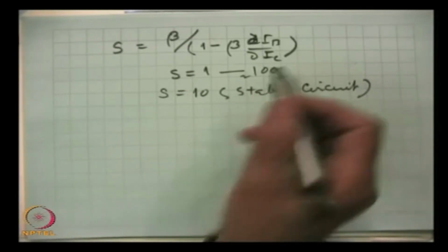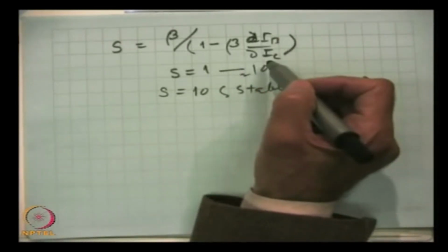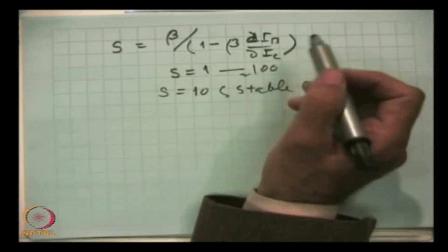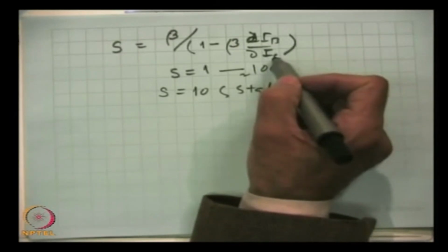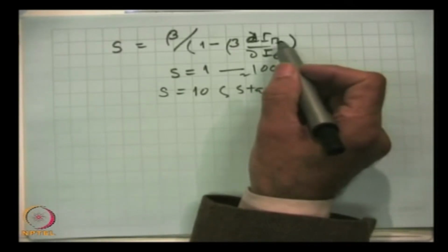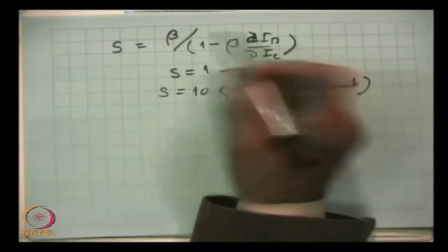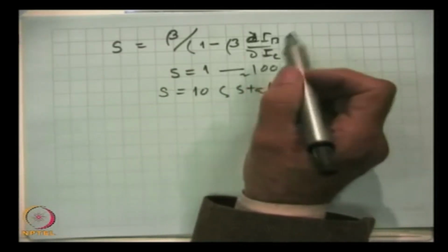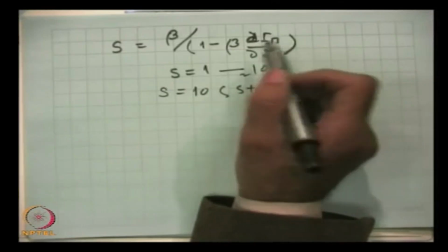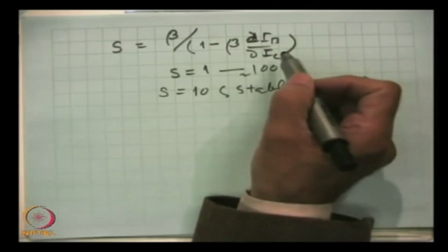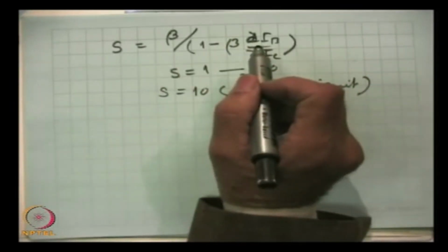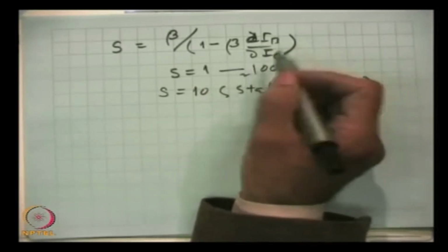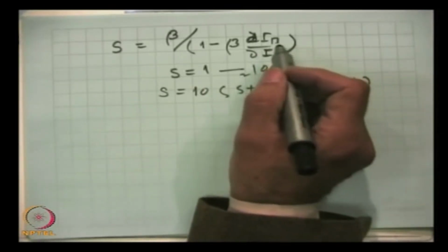So, what does it basically say? That in all circuits, when the collector junction is reverse biased and the emitter junction is forward biased, the output current will be a function of the input current. But here this says differently, that the input current should be made a function of the output current. When this happens, then we can achieve stability. I will explain this point further, and this is achieved by using negative feedback.